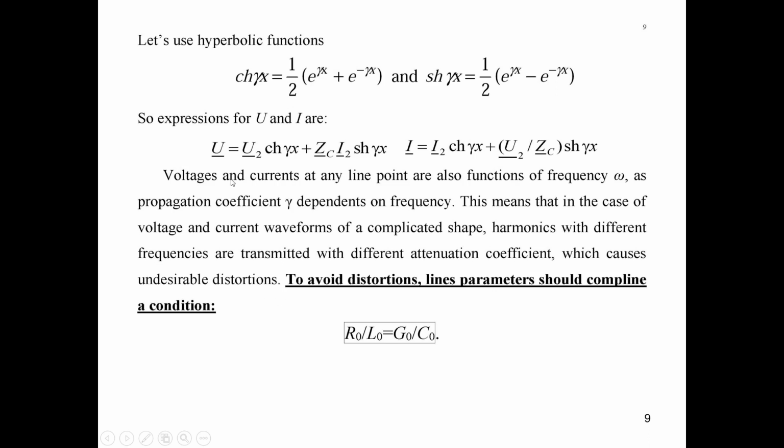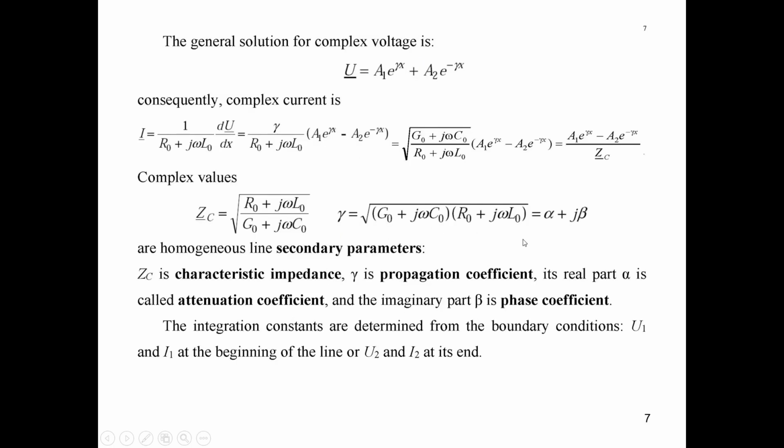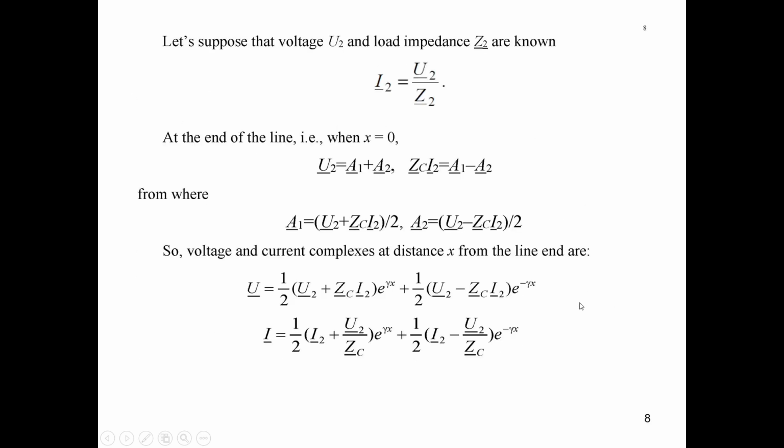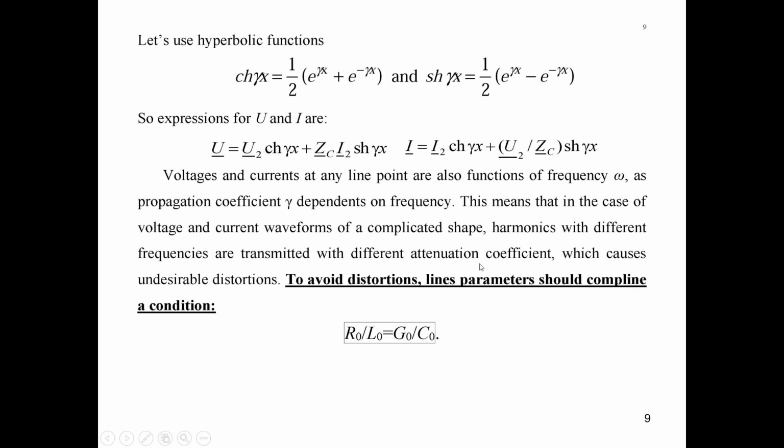So here we can see that currents and voltages at any point are functions not only of the x coordinate but also of frequency, because the propagation coefficient gamma depends on frequency, and both its real part and imaginary part, the attenuation coefficient and phase coefficient, will depend on frequency also.